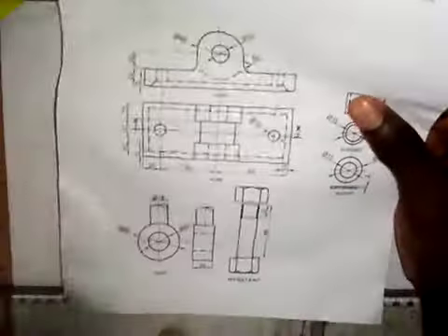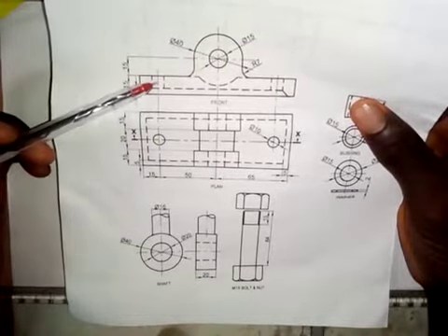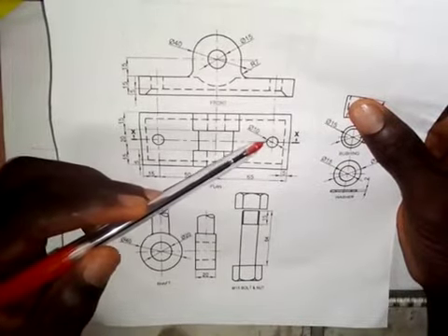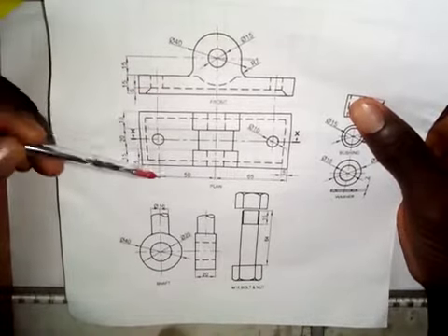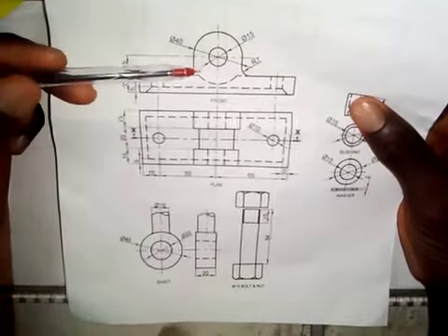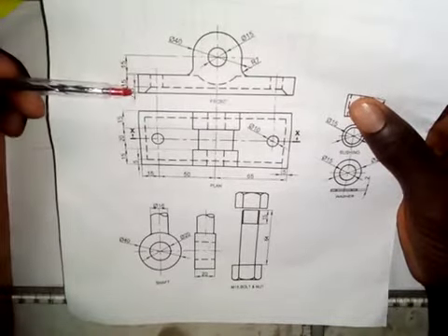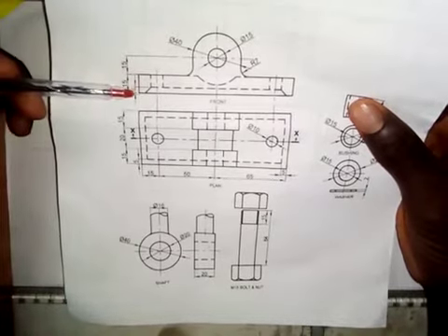Now the next thing I'm going to do is this. Looking at what we have here, we have this hole in the plan. It is hidden in the front elevation. So we have these two holes, and the diameter of each hole is 10 millimeters. By the time this part is cut off, we are going to see a line under here. It is hidden in the front elevation, but by the time we cut it off, we are going to see this line under here, and the distance from here to here is 5 millimeters. So let's first of all take that.